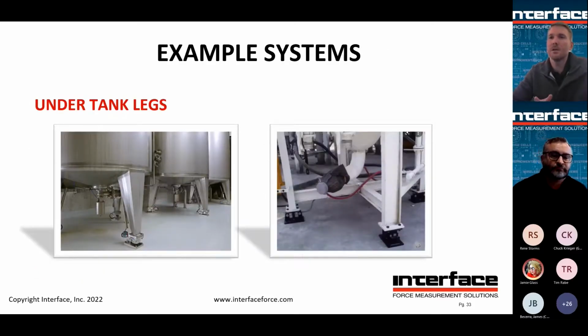So just a couple good looking installations here. If you can get in on the front end of design, it's always a good idea to get with the tank manufacturer if possible. A 3-leg system will ensure equal loading at each point. Picture your stable milk stool versus a wobbly 4-legged chair.